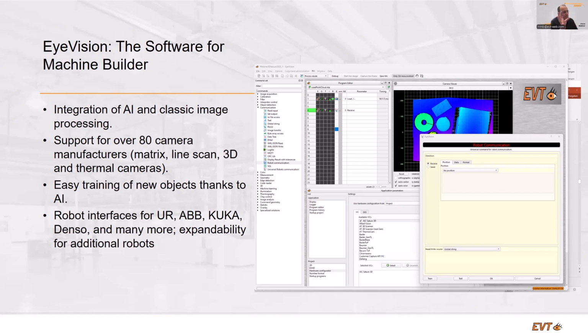So if you have a certain task, you can select one of the predefined robot interfaces, or of course the robot interface is based on a flexible description of the robot communication. You can add nearly every robot which is right now on the market, which has a standard communication format and interface. That means interface means either RS-232, USB, gigabit Ethernet, or let's say Ethernet, and within these protocols, one of the communication parts. So you can set up any kind of interface to the robot.